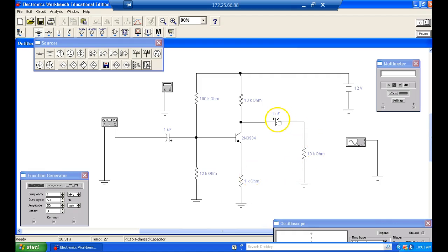When I short this resistor right here, that 10K is now part of the circuit. Okay, so they get some of the voltage. It's a path. So what happens, we have two paths now. We have current flow here going through there. We have current flow here going through there, which means the 10K is going to drop more voltage. If the 10K drops more voltage, that's going to be less DC right there, right? So I expected it to do what? Go down, which is what it did.